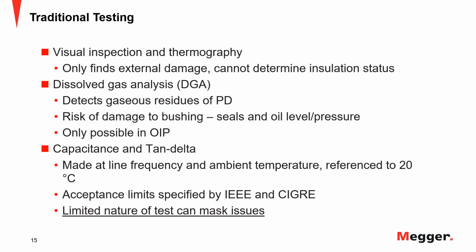And then I think that we have to emphasize the value of capacitance and tan delta testing, or power factor testing. Typically, what we do is a line frequency test, what we call the 60 hertz or 50 hertz, depending on where you are. You do a test at the temperature that you are running the test. In different activities, I have asked attendees, how many of you have tested a bushing at 20 degrees C? And I've never seen somebody raising the hand, which tells me that you're always testing at different temperatures, right?